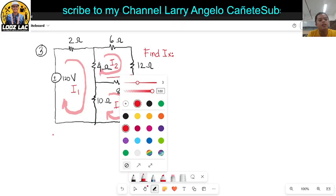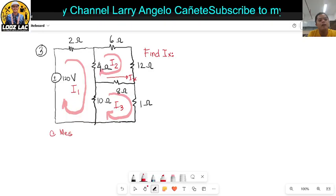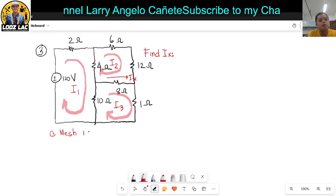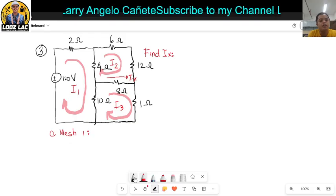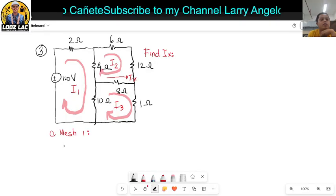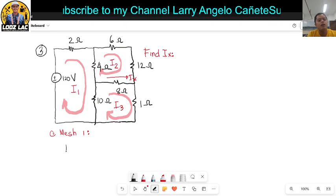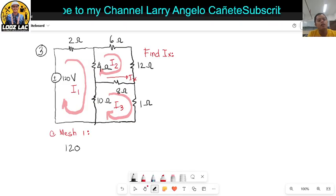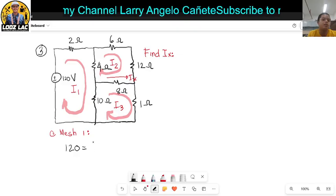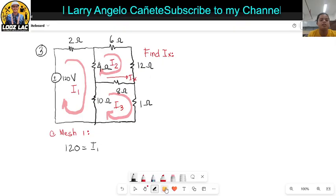At mesh 1, for the equation, we have a voltage source, so it is positive: 120 is equal to, since you are inside mesh 1, I1 times the sum of all resistors inside mesh 1.